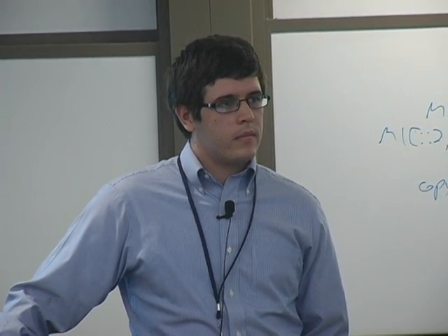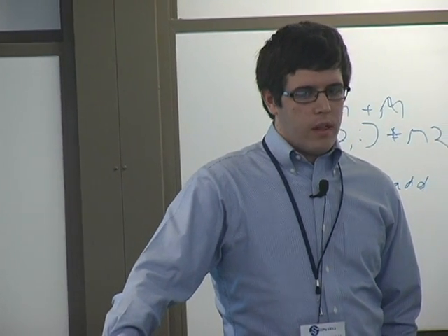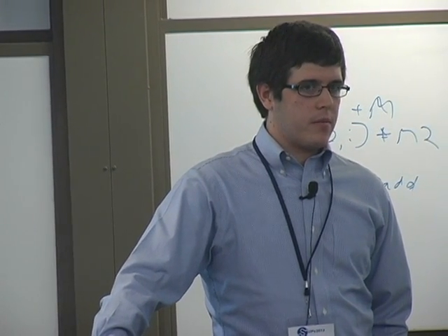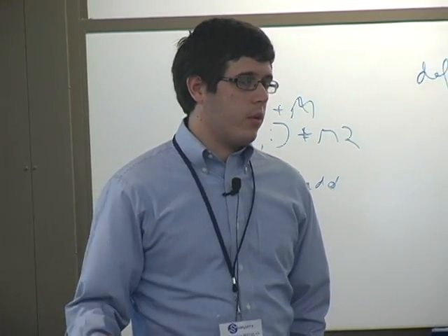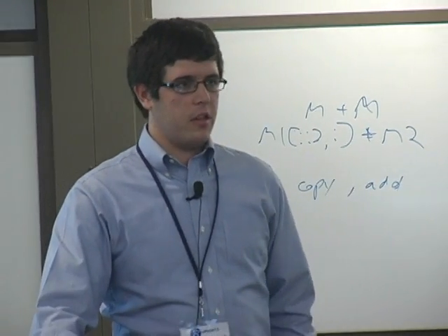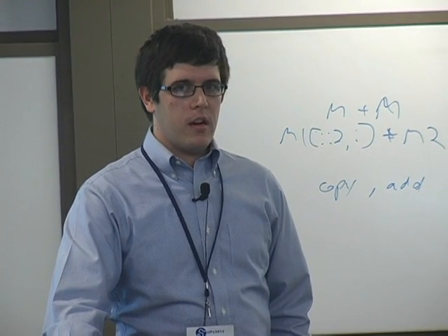Yes. You guys are using first order differences there. If you use any higher order on your discretization, do you have a problem with interpolation then? You mean for generating the initial coefficient matrix? Mm-hmm. Well, that was just a sample problem. I think multigrid algorithms can take any coefficient matrix A and work on it, but I think convergence has really only been proven for elliptic problems.